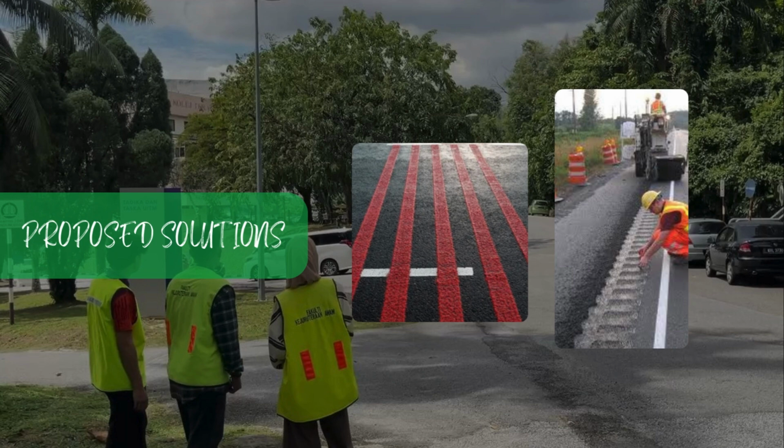Lastly, we can add traffic calming measures such as rumble strips. Rumble strips can be installed on the downhill approach towards the kindergarten. The vibration and noise from the strips act as a warning to drivers that they are entering a sensitive area, encouraging them to slow down naturally without causing discomfort. Overall, these measures work together to help reduce speeding and improve safety around the school zone.